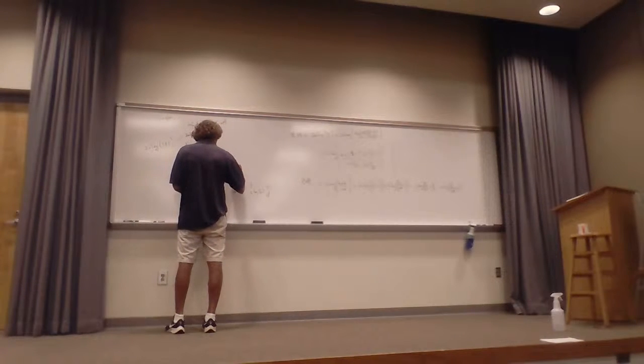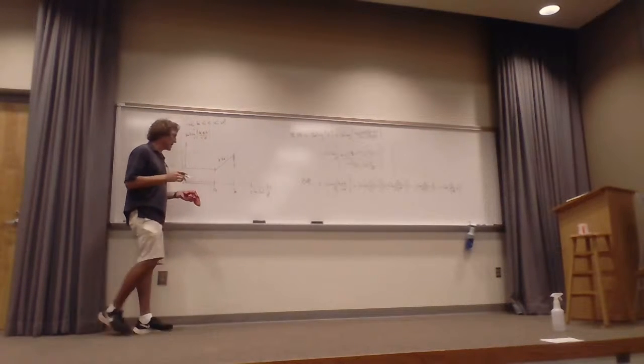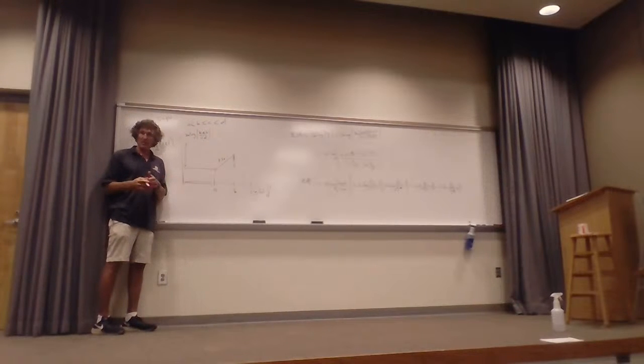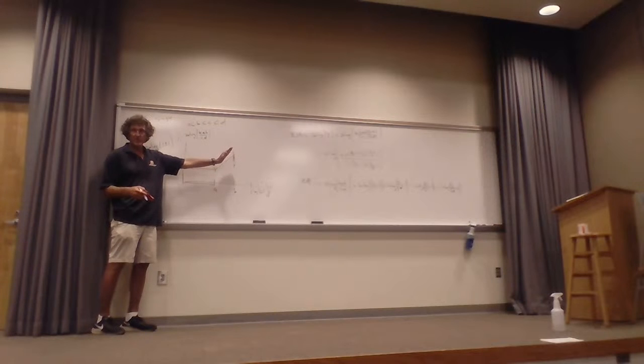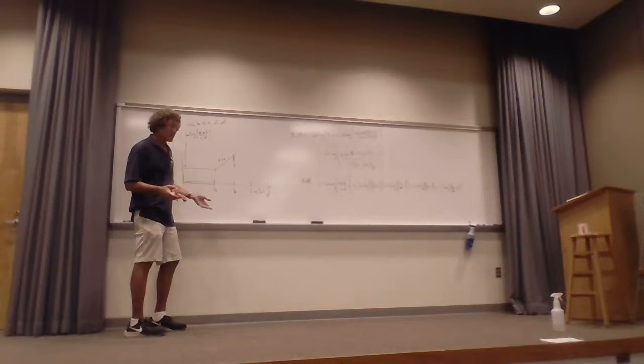Then from here to here, I'm going up at a rate of plus 20 dB per decade. I don't know how far I've gone up. I'm going to show you how you calculate that in a second. I just know that's the slope of that line. You with me? Because I didn't give you a relative value in A and B.